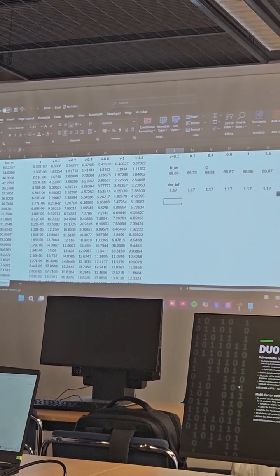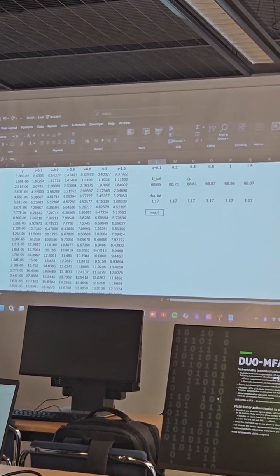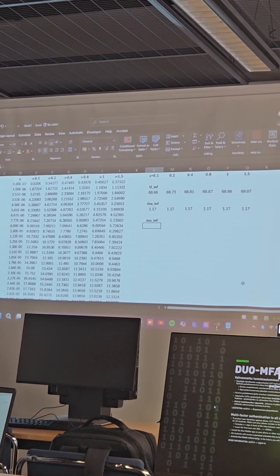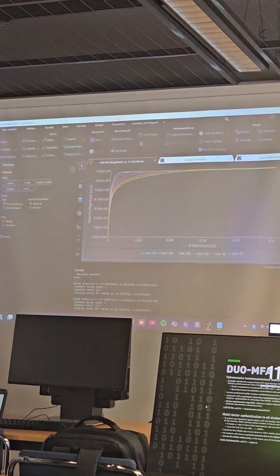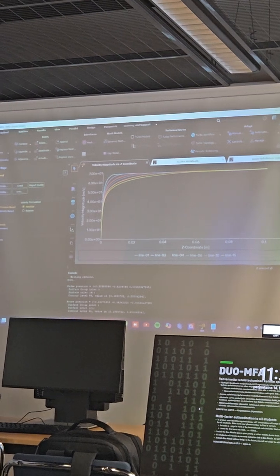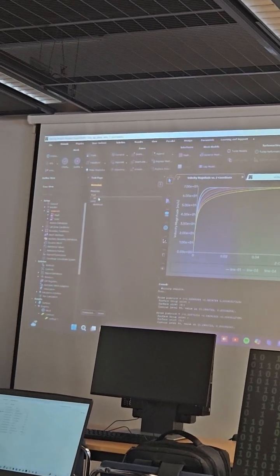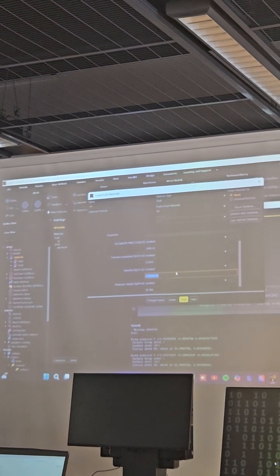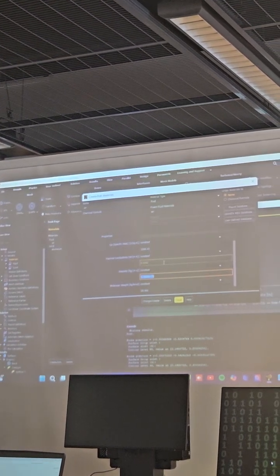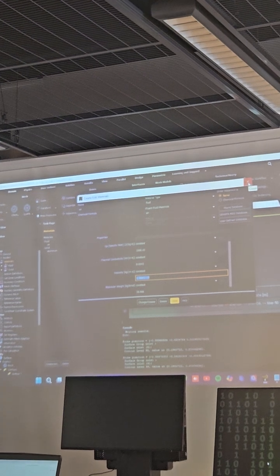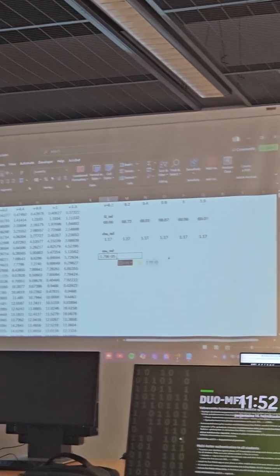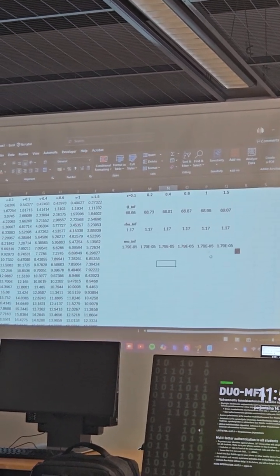And then we need dynamic viscosity, also mu infinite. So you can find this value in Fluent. In the top here there is materials, air. So we simulated this case with a viscosity. This is the dynamic viscosity, and this is the value. So 1.789 10 to the power of minus 5. So I copy this value in my Excel. And this is also a constant, so it's the same for all the cases.